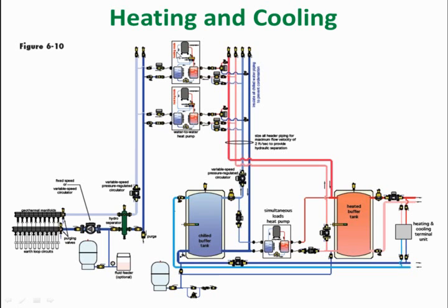But now if both of these were running for heating cooling applications, we could put another heat pump in there and really get some real high COP. We get the COP on this thing up around 7, because now we put a heat pump in here that would supply heating and cooling at the same time, what we'll call a simultaneous load heat pump. So what that does, it increases the efficiency of that heat pump by having both loads on at the same time. Now, again, a little limitation on that is both those heat pumps above would have to be in the heating and cooling for that to be able to work right.